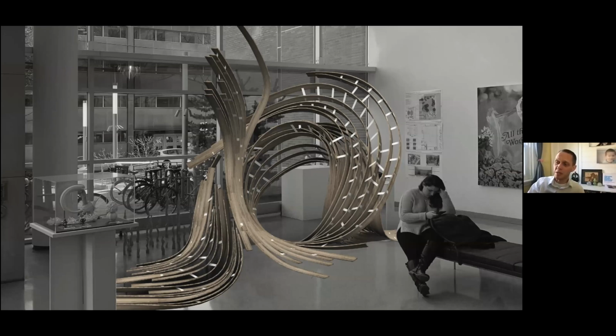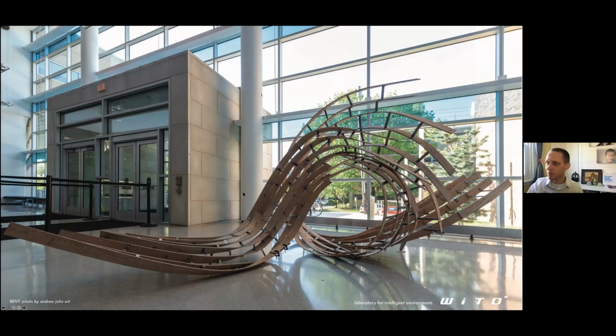And basically those pieces were these little brackets that were held together in this small prototype that we built. This is the final piece. There was not a single drawing for this. It was all done digitally and then physicalized using the HoloLens. There was very little waste in this project also, because through computation, we were able to set a series of board lengths, and then optimize the entire system so that you don't waste any of the pieces as you're assembling it together.